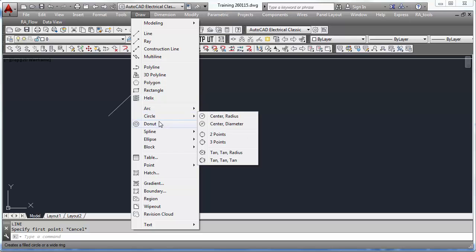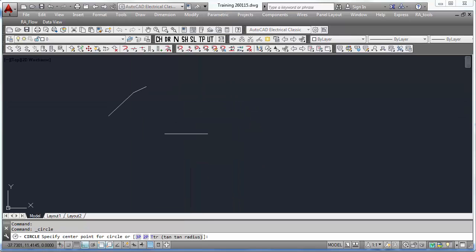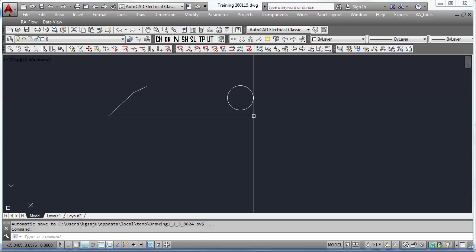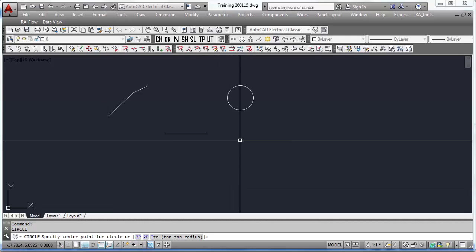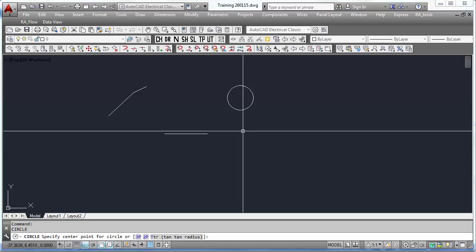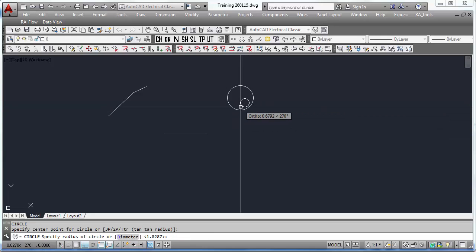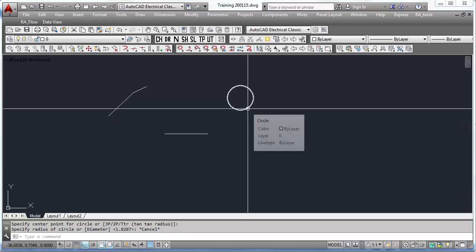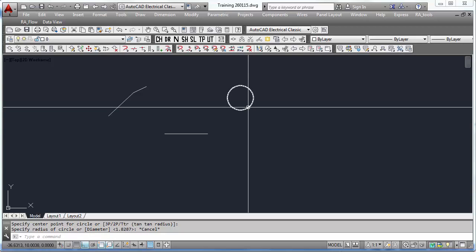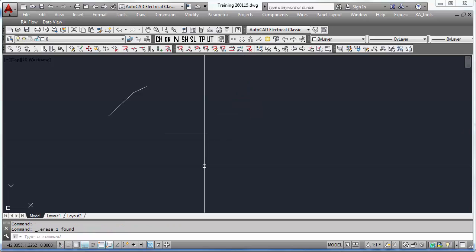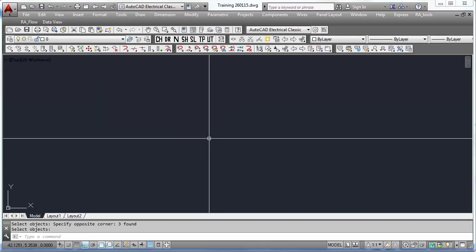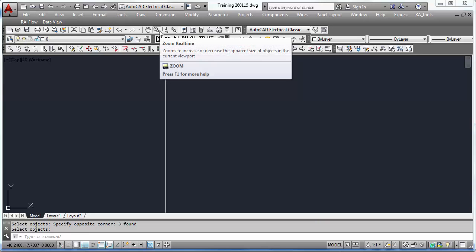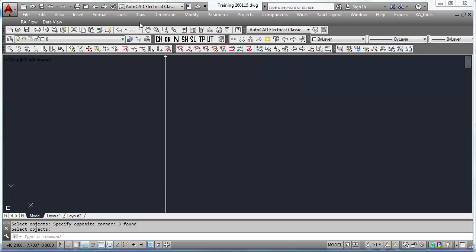For example, I am drawing a circle here. Now I am pressing enter. See in the command line, circle, because I have last given the command circle. Got my point? In order to repeat the last command, you just press enter. So now you have learned how to draw a line without a dimension and with the dimension.